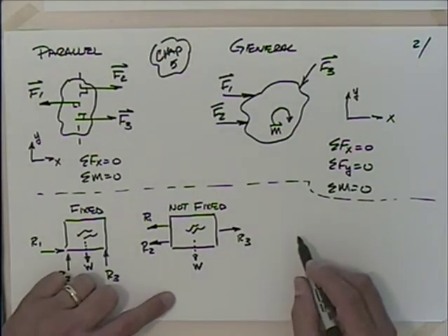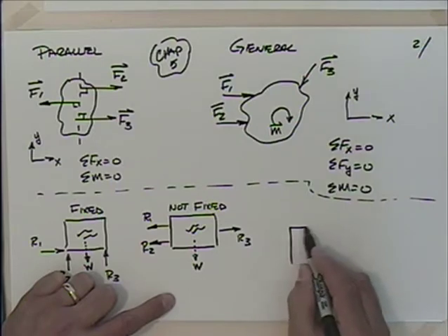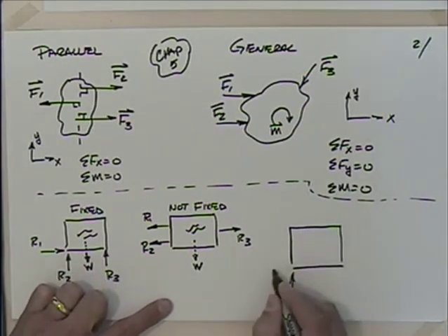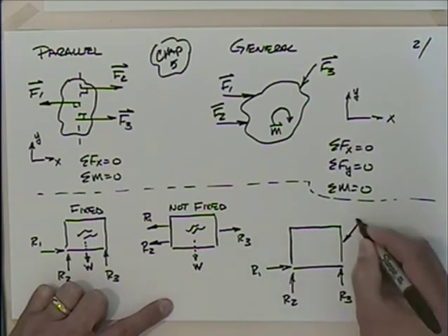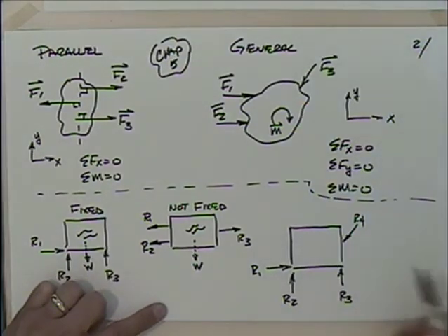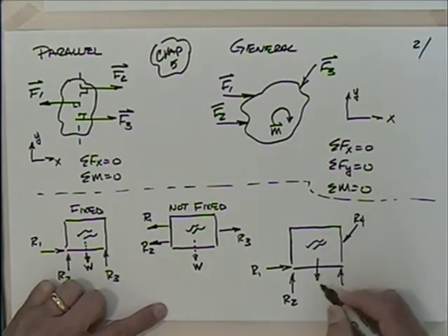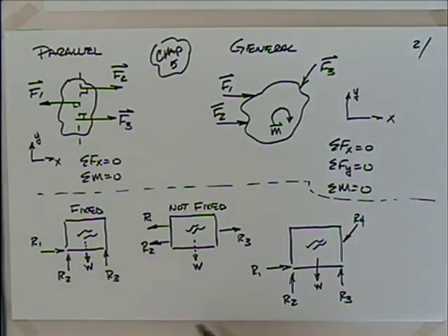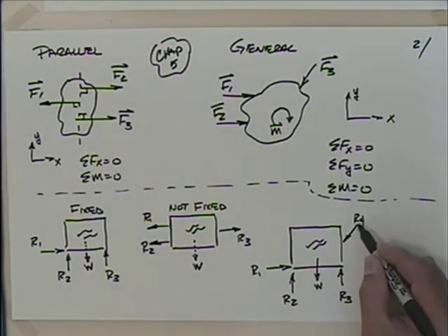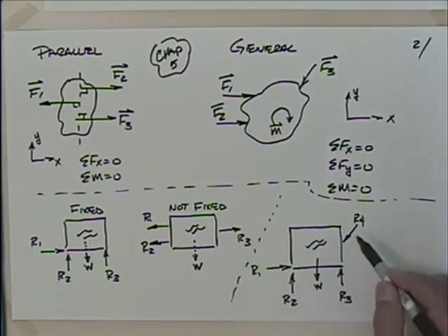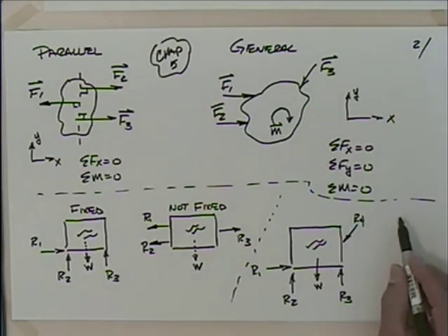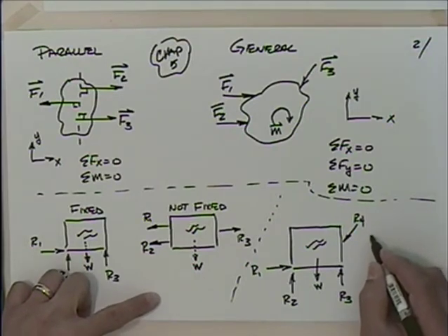And the last case is probably the most important case that we'd be able to recognize. Let's say that we took something like this first one, and if a little is good, a lot is better, so maybe we'll add something like this, R1, R2, R3, and R4, putting so-called belts and suspenders on the thing. We've got it constrained like that. But remember, if the weight is the only thing that is maybe known here, we would have an unknown in R1 and R2 and R3, which was not a problem over here because we have 3 equations, 3 unknowns we can deal with. But here we add this fourth, we have a 4th unknown and we have a problem. So unless we can make some assumptions and neglect one of these, say it's very small in comparison to the others, we are forced into a situation where we have only 3 equations and we have 4 unknowns, and we will call this a statically indeterminate situation.